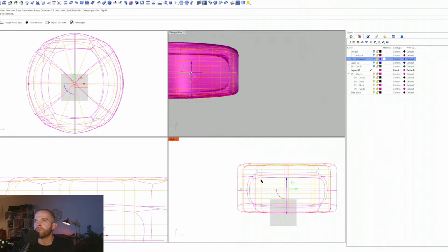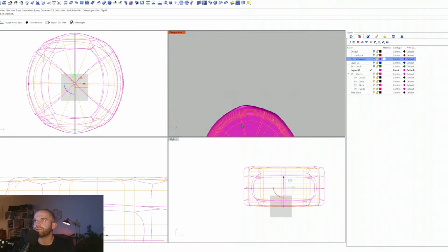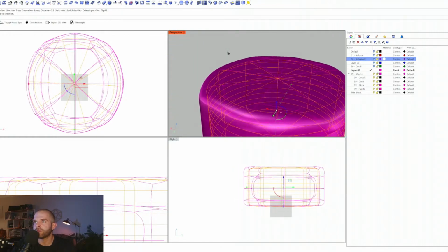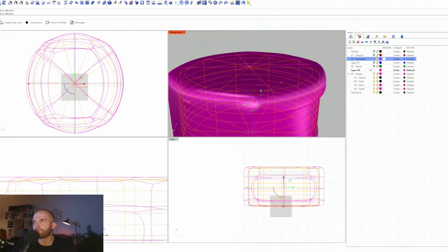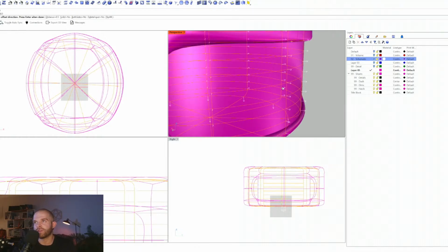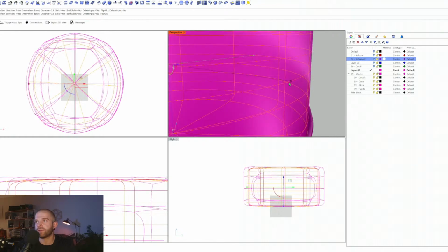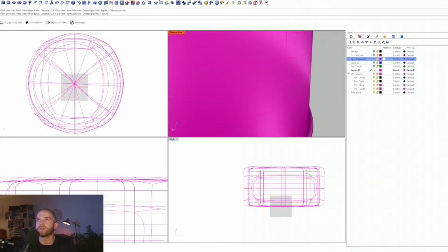Okay, so if we select that, we should have what we see from the top. Oh, it just offset it outward, so it didn't make it right. So if I undo that, we do offset SubD. What went wrong there is I intended to give it a thickness, whereas all I did was expand it outward, which is what it's doing. Offset SubD to expand outward, and that's because I hit keeping it solid, which I do want to keep solid, but I don't want to delete the input, because now when I have both, I can use my SubD